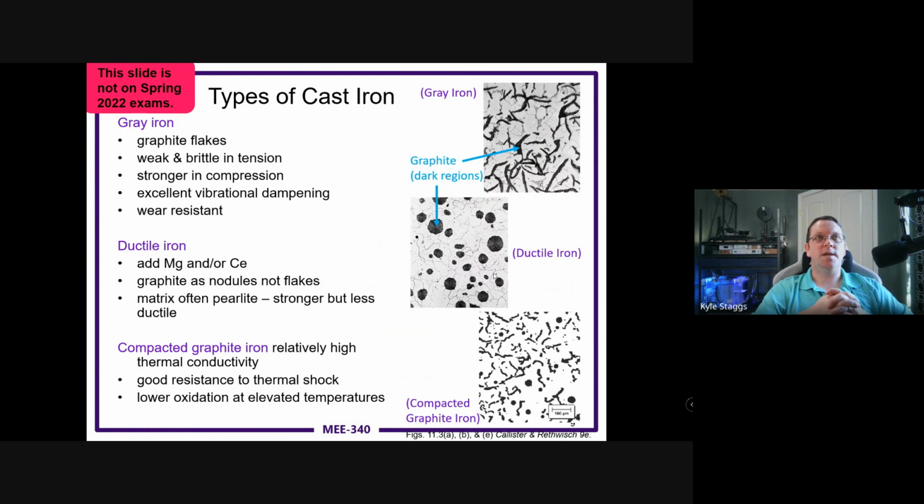It's very weak, and it's brittle in tension. So this is why you don't see like cast iron pillars made these days. And when they built stuff out of cast iron to be structural, it was always big and massive and heavy. And so cast iron gates and things, they're just massive structures with obscene weights because they had to be thicker in order to be stronger in all the right dimensions.